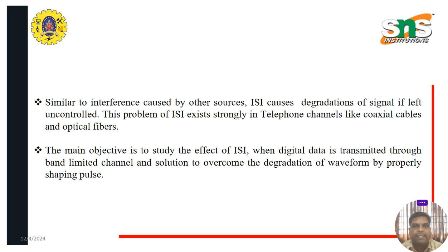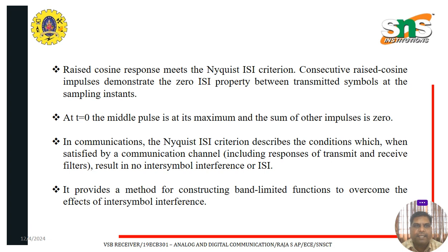This problem of ISI exists strongly in telephonic channels like coaxial cables and optical fibers. The main objective is to study the effect of ISI when digital data is transmitted through a band limited channel, and a solution to overcome the degradation of the waveform by properly shaping the pulse. The raised cosine response meets the Nyquist ISI criterion.